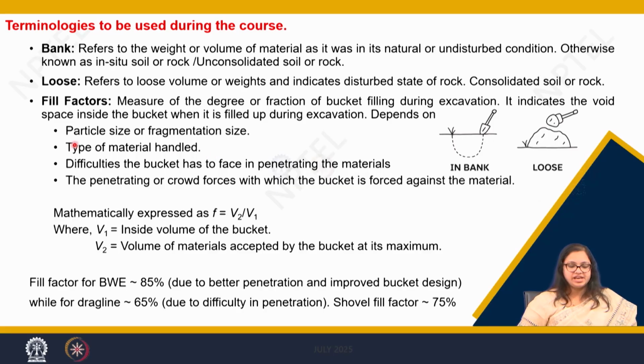And if it is rock with different particle sizes, there also your fill factor will vary. The third factor on which your fill factor depends is the difficulty the bucket has to face in penetrating the material.